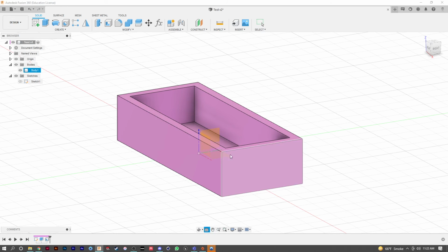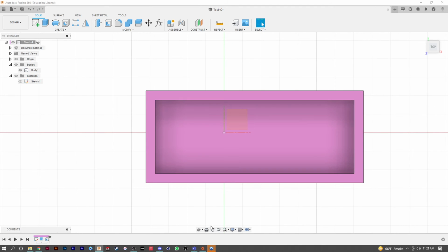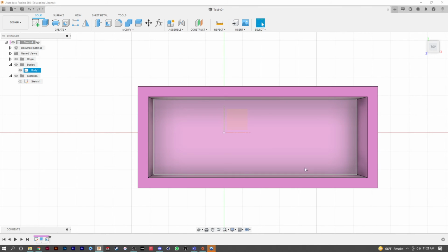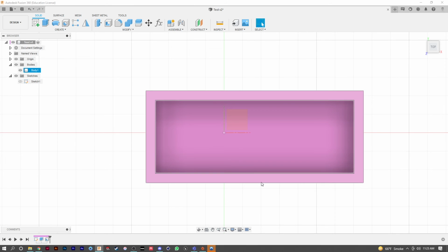All right, so now we've also got look at here, which will allow you to grab a sketch, for instance, and we can look at it. So if we hit that, it'll take you to a planar view of it. The planar view is really useful because it's a perspectiveless, for the most part, view. Sometimes you'll get perspective in your scene. You don't want that. Just for what it's worth, you'll know when you see it. You'll get foreshortening if you make a cube. If we set this to perspective mode, as you can see here, we're getting foreshortening where we can see these edges here, which is actually really, really annoying. So I would recommend sticking with orthographic almost always here in SolidWorks.